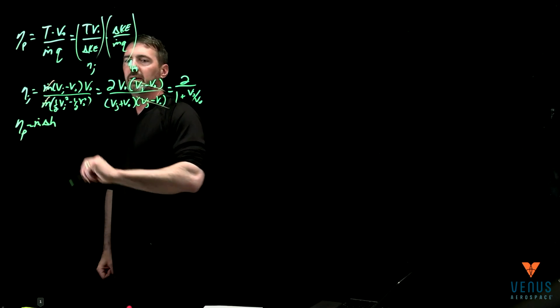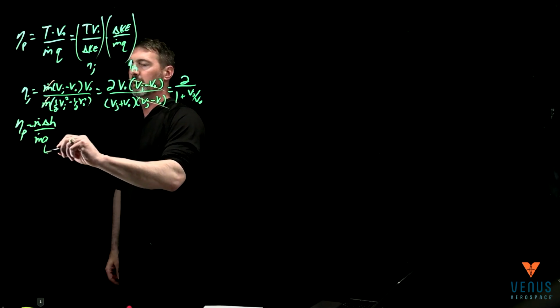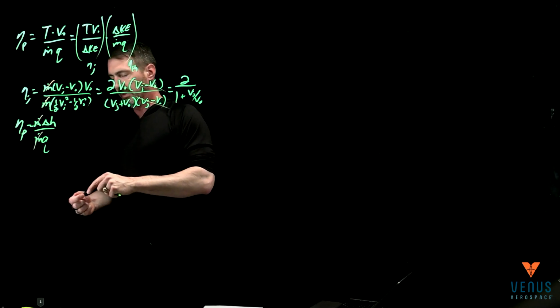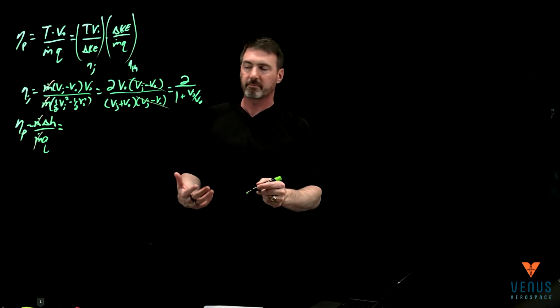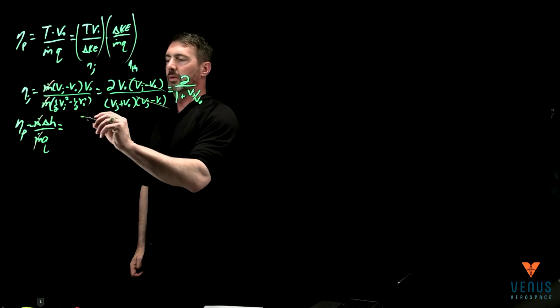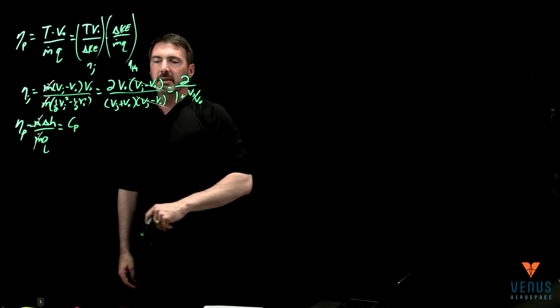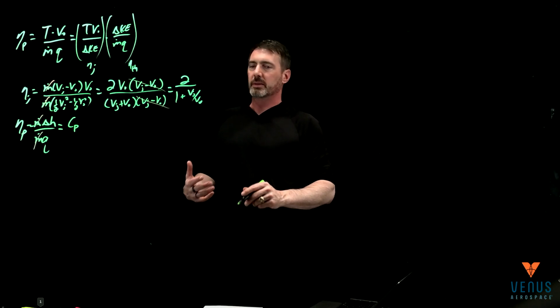There's an m dot because that's a little h, compared to the m dot Q. Again, the m dots cancel out, which is fantastic. And then this is ideal gas, so we'll say this is Cp times the change in temperature. So a couple different ones.